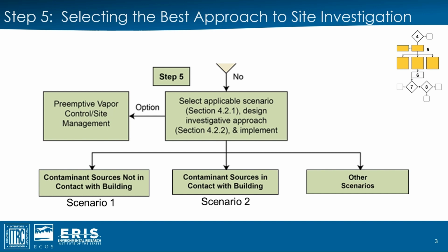However, if the contaminant source is in close contact with a building, or there's a preferential pathway present, then sampling indoor air or subslab vapor is generally preferred. Identifying and eliminating potential background sources in indoor air can still be challenging, however. In such cases, it's often beneficial to conduct an initial walkthrough indoor air vapor survey using a handheld PID or GC prior to indoor air vapor sampling.